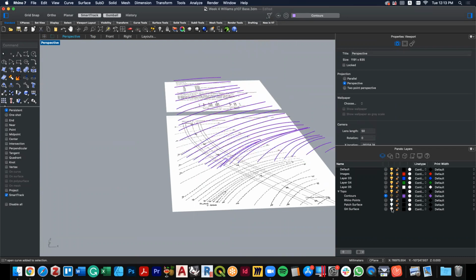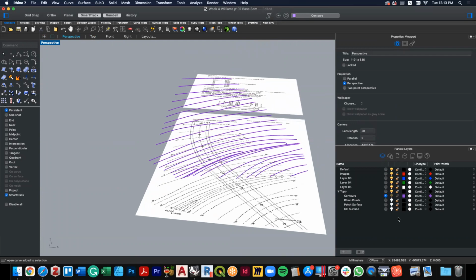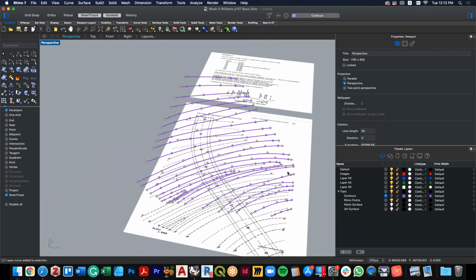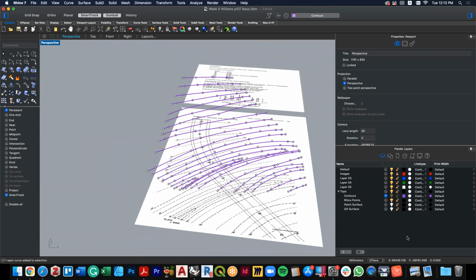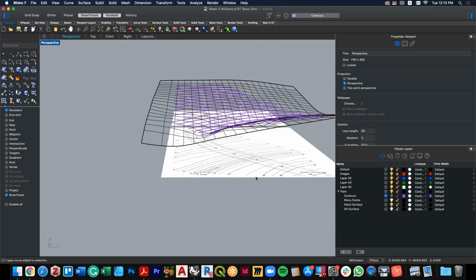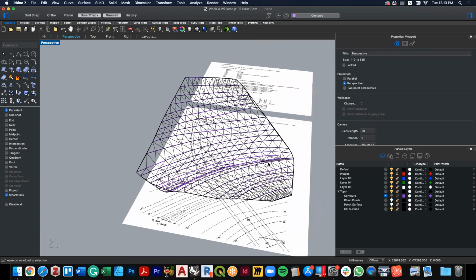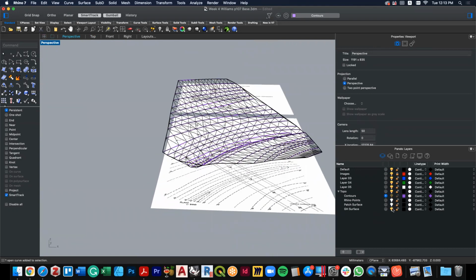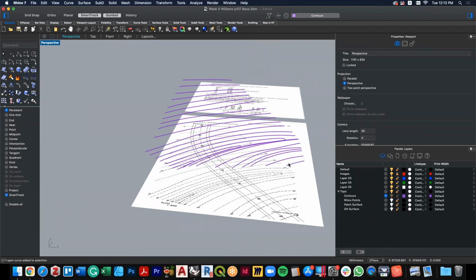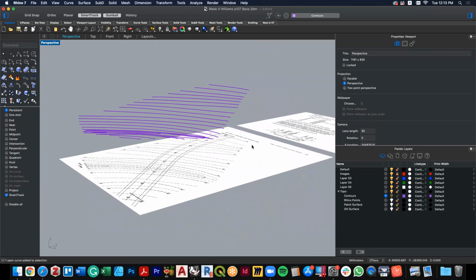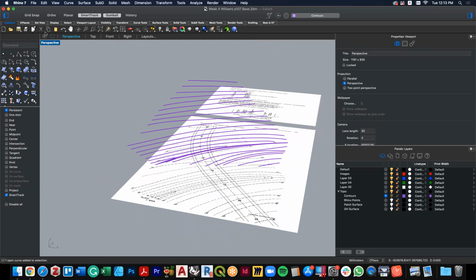I've also created a surface. The way that I've been doing it previously is to use the extract points command on the contours to get a series of points, and from that I've created a patch surface. But I've also created a Grasshopper surface as well, so I've got both of them there now. This is not so important right now, so rather than explaining all of this, I'm starting with contours lifted into place and surfaces already undertaken.